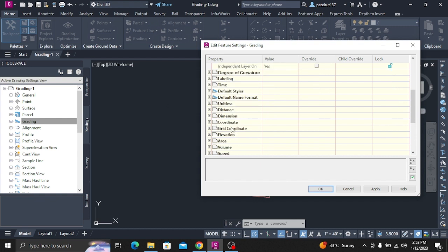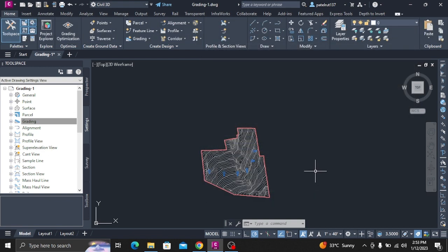Target, distance. Distance, 10.000 foot. Projection, slope. Format, grade. Grade, -6.000%. For the grade parameter, click to change it to locked. When you lock a grade value in a grading criteria, you are not prompted to specify its value each time you use the criteria. Click OK.